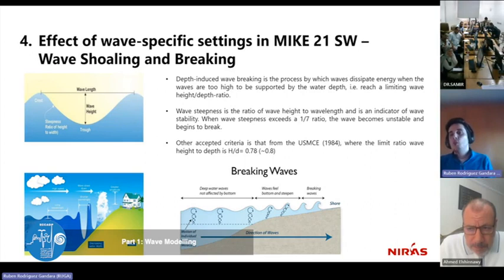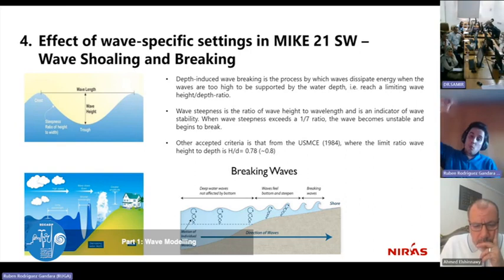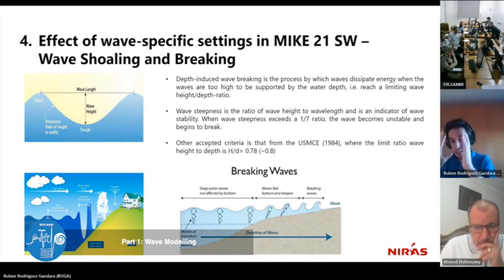And it is very intuitive to understand that as you go into shallow water, the wave will not be able to go down in the step from crest to trough. It will not have room next to the seabed to allocate all of that water, so the crest will increase in order to allocate it. And that is basically showing you wave growth near the coast. You know all about this: those waves cannot increase indefinitely. You will not have a wave height near the coast of 100 meters or 20 meters.